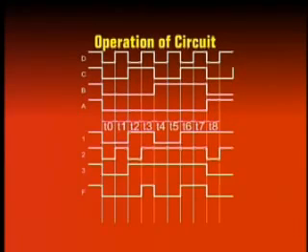At interval T0, the input A, B, C, D to the circuit is 0, 0, 0, 0. The outputs of the 3 OR gates are 0, 0 and 0, and the circuit output is also 0. Now this can be seen in the timing diagram. For interval T0, the timing diagram 1, 2, 3 and F shows logic 0.